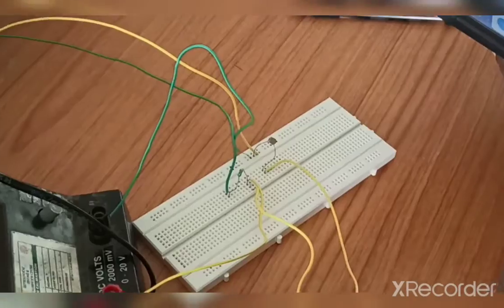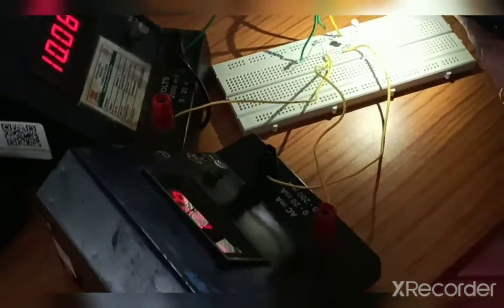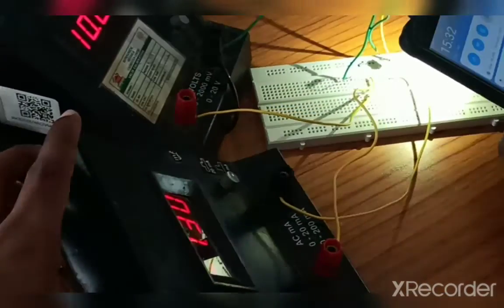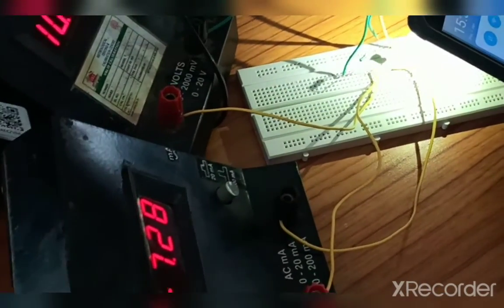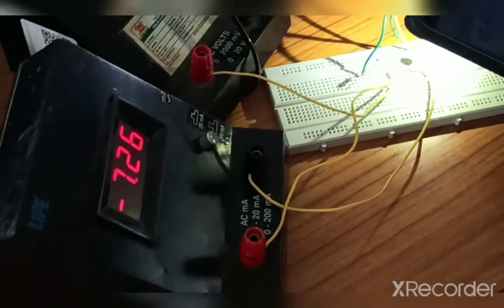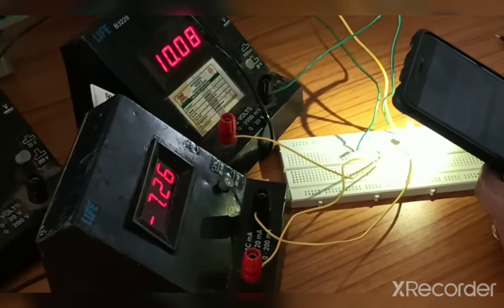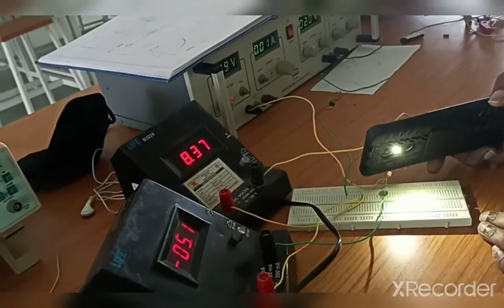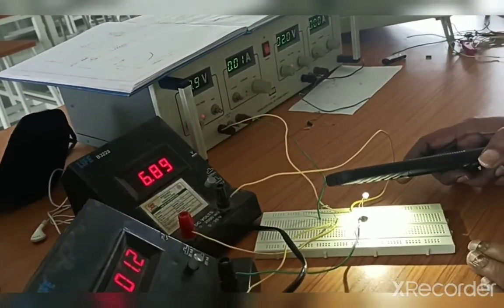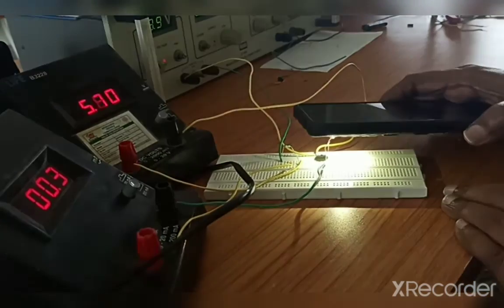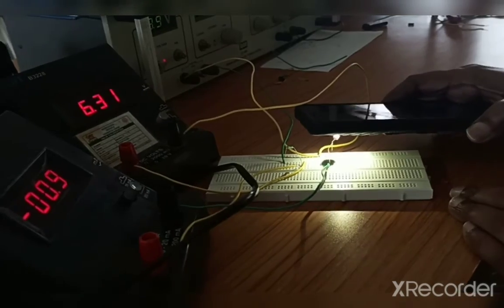So what is the procedure? First, rig up the circuit as per the circuit diagram, and a sinusoidal input signal of 1 kilohertz frequency and amplitude of 8 volt peak to peak is applied from the function generator. The peak amplitude of the input must be greater than the clamping level. Display the output on the CRO, compare it with the given waveforms, and increase the input further. Note down that the output peak is clamped to the desired level.